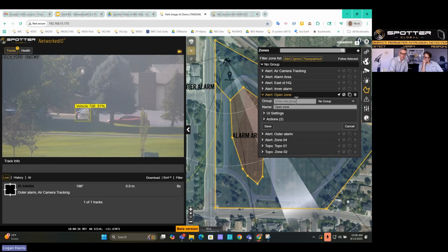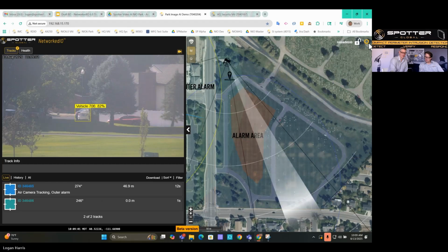So right here, you can see that I just have this alarm zone in this area. Okay. So things in this area out here, I filtered those out with an SNR filter. So what is basically an exclusion zone. So I've said these busy roads, I just don't want to see them. Okay. And because the radar can measure exact position, I can filter all of that out. Nice.